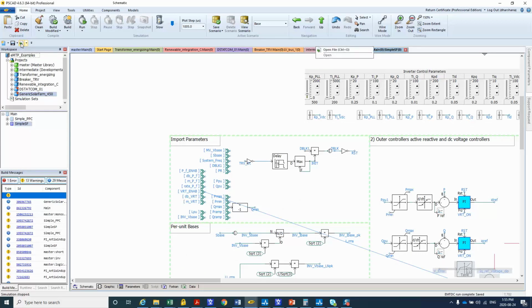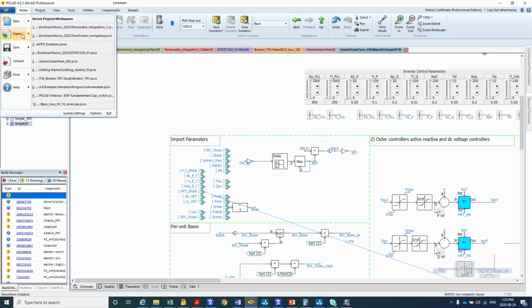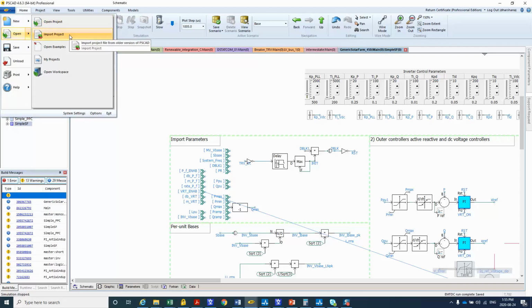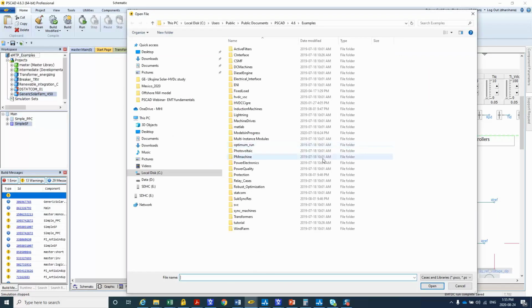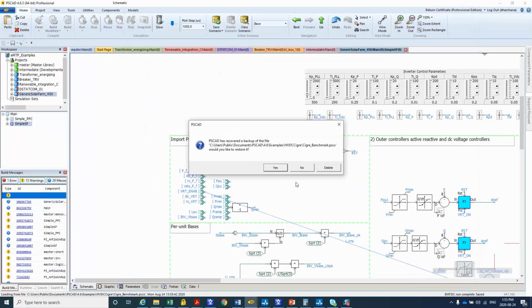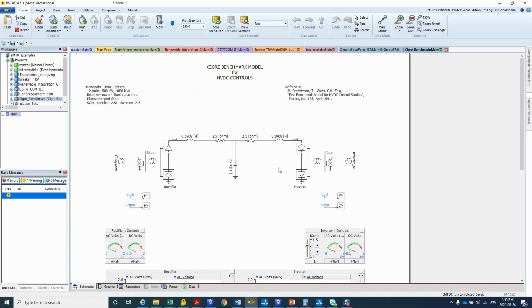Finally, I will show you an example of an HVDC system. I'm going to show you a very standard example of the so-called CIGRE HVDC benchmark. And for most generic type studies, most studies that engineers would do, we would use a generic model, generic example, and change the ratings and basic parameters to reflect our specific installation or the device.